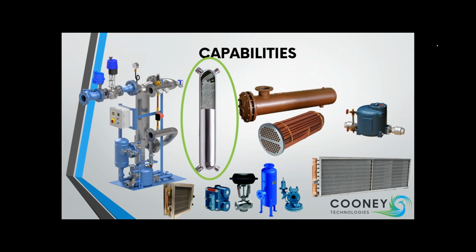If you aren't on a district energy system, if you're returning your steam back to the boiler room to be regenerated, it's a good idea to just use the subcooling aspect to reclaim all the sensible heat from your steam. You're paying for it. You might as well get the BTU benefit out of it. And as your condensate comes out at a lower temperature, it's a lot easier once it reaches your vented receiver. If you have a simplex or a duplex electrical pump receiver, it's a lot easier on your pump seals. It's going to make them last a lot longer.